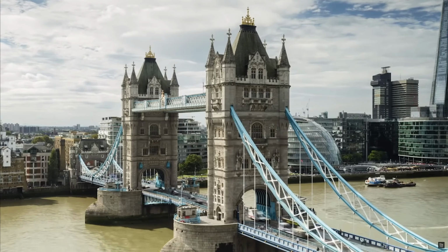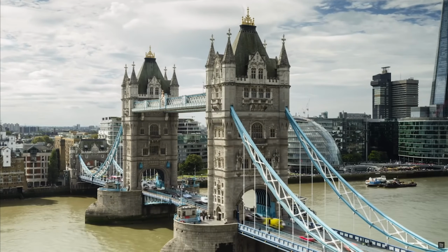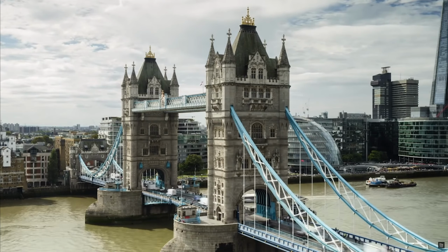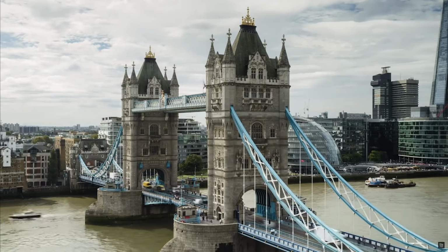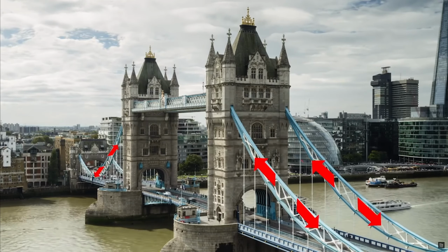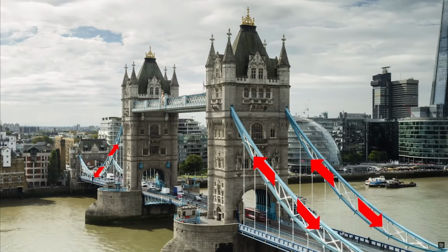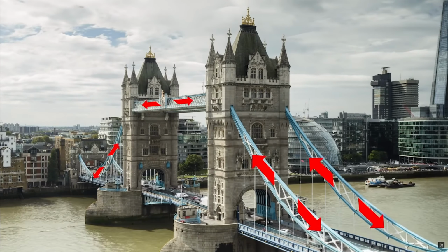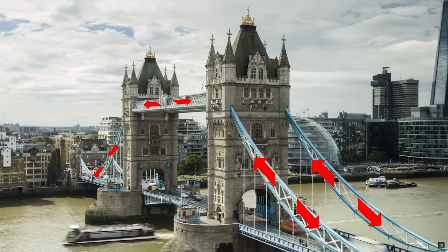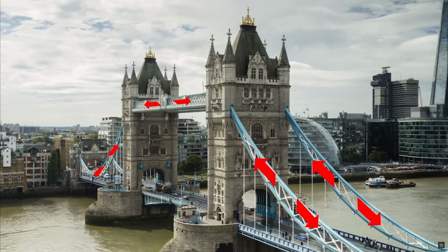But what's interesting about the tower bridge is that there is also a walkway bridge at the top, which in and of itself acts as a connecting member between the two towers. Because the outsides of the towers are suspension bridges, they are experiencing sort of a pulling force that's attempting to pull them apart. Therefore, the walkway that is connected at the top is acting as a connecting member that's experiencing tension itself, keeping the top of the towers also aligned and in place.